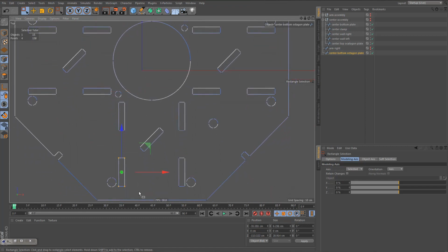And let's check these ones as well. So this one again is 14. This is 12, 12, and what did we have here? 13. So we changed everything to 13. So I'll just copy that, and I'm going to make these holes consistent, because we need to rotate the arm construction around, and all of these holes need to have the same length. And once we've adjusted the length of these openings, we will have to adjust some points on the arm, and then we'll be fine. So let's see, I'll change all of these to this number here.